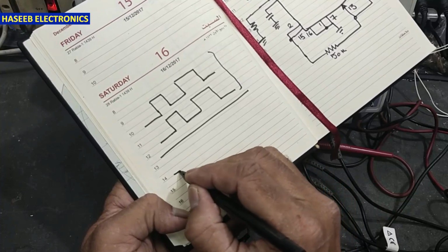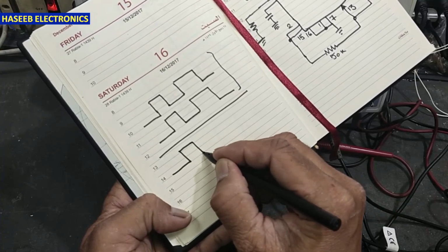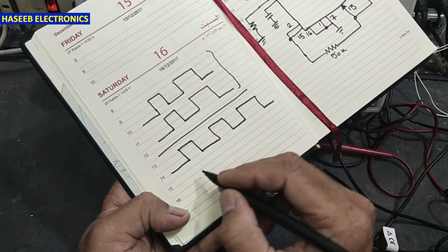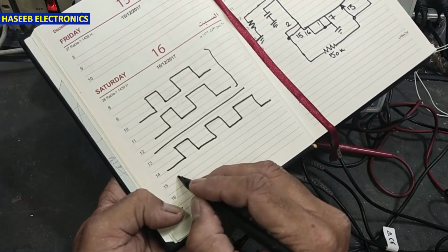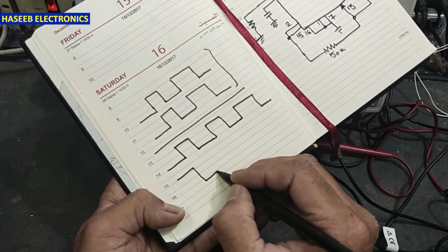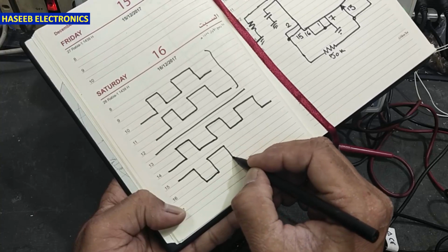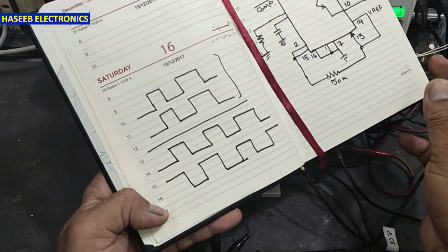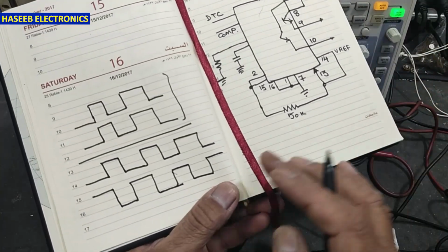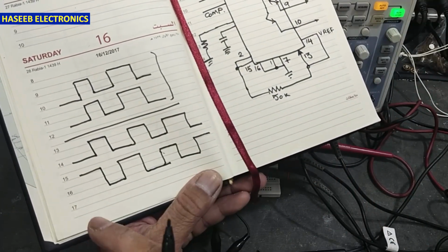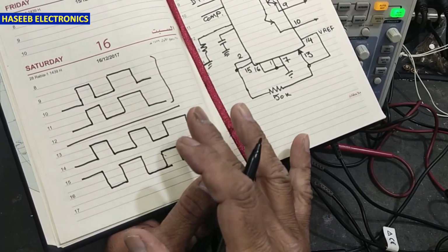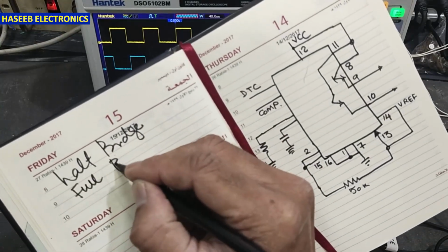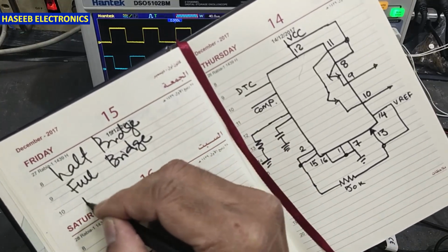When we say push-pull, that means one will go high. This is one MOSFET, one transistor, one output. In that time, if this is low, the second will be high. These will work opposite to each other. And I configured the circuit in that video. That was part 1 of that series. It is push-pull. It has to drive two MOSFETs. We can use it in half bridge, full bridge, or we can use it in push-pull.